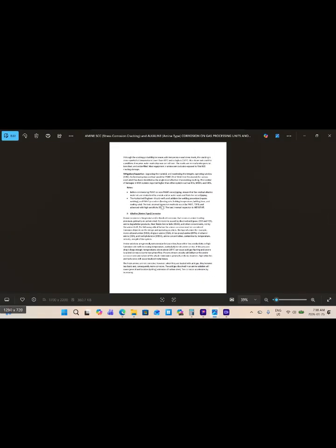Normally, amine stress corrosion cracking happens on carbon steel. The cracking probability also increases with temperature and stress levels.